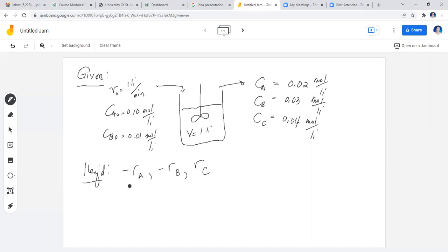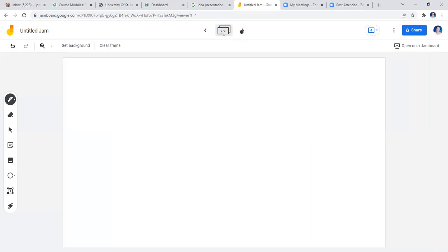Okay, so this is an MFR or a CSTR. That tells us that our working equation will not need us to integrate. So our working equation is tau, because we have a flow reactor, equal to CA0 XA over the rate. And this particular tau is equal actually to V over V sub 0.